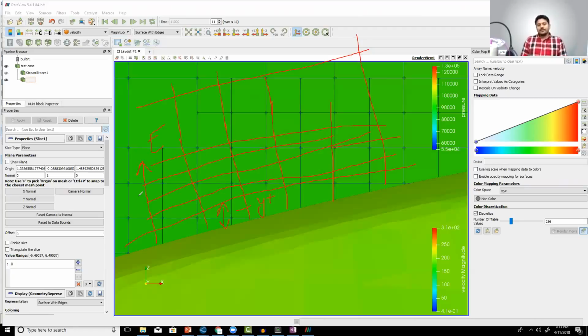Shazad, a difference between steady and transient analysis. The idea behind steady state and transient is quite simple. In both cases, you are actually having time steps. Even in steady state simulations, there are time steps and intermediary solutions. The thing is, the intermediary solutions are not being solved accurately. Since your final results are important, you try to take really large time steps and get to the end time as fast as possible.